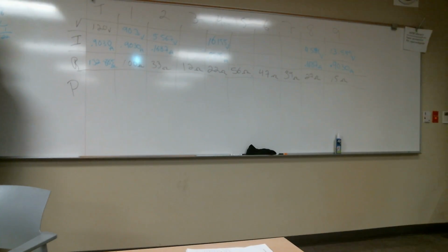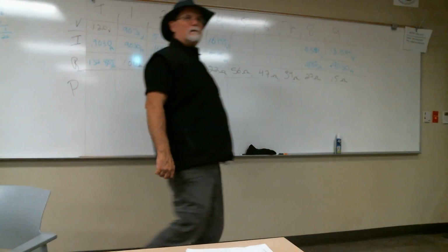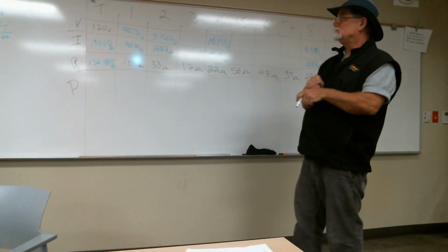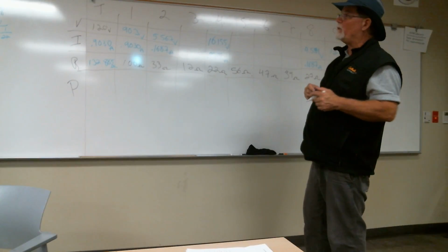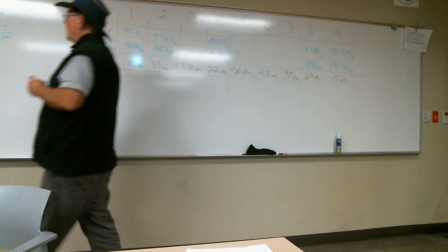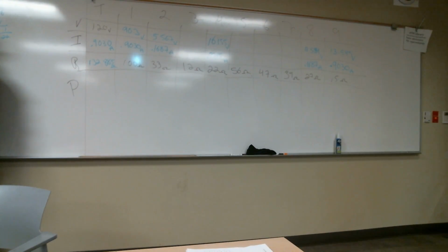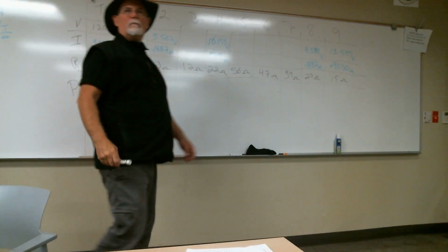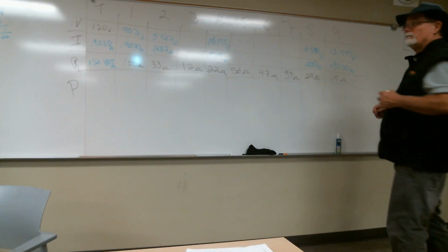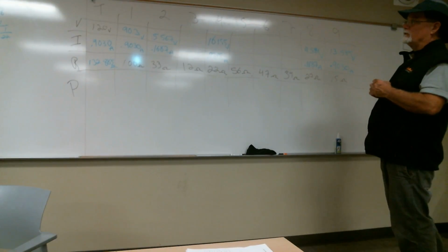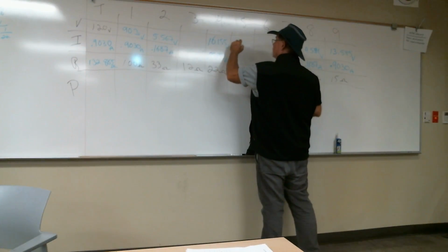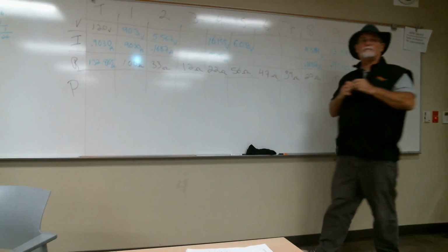The voltage drop across R5 is going to be the difference. I'm going to take my node voltage, 24.133, and subtract 18.099. Should give me 6.1 something. 6.033 volts being felt across R5.